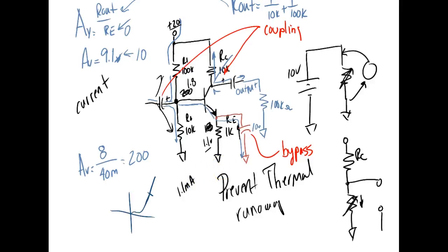No, we're not concerned with that. We're calculating RE prime. We're through. All we need to calculate RE prime. So RE prime is equal to 25 millivolts over IE, which would be 1.1 milli. So what's RE prime? The milli's going to cancel out, right? We got it on the top and the bottom. So it's going to be 23 ohms or something like that, 22 ohms.